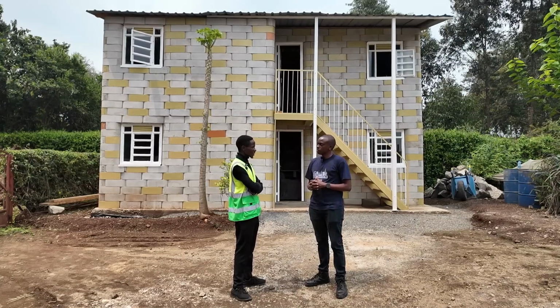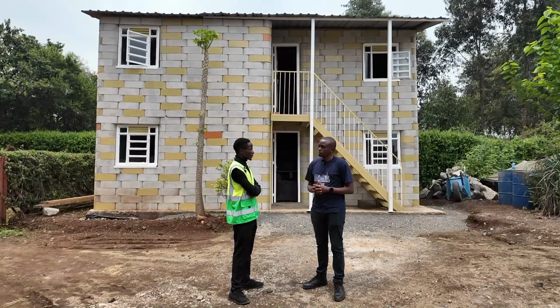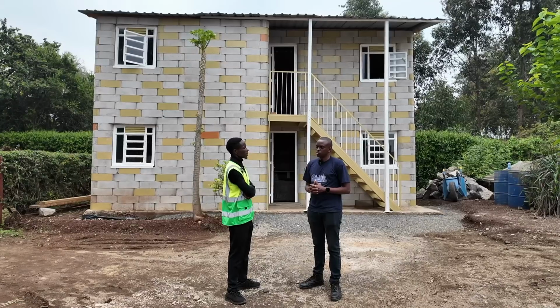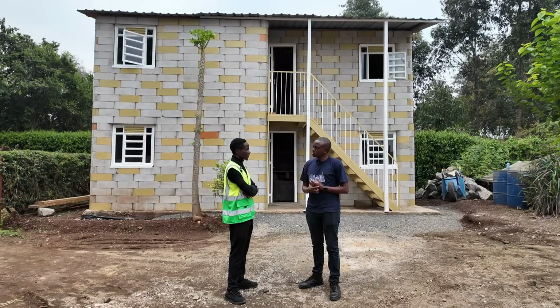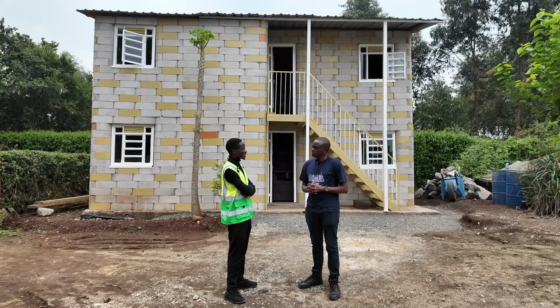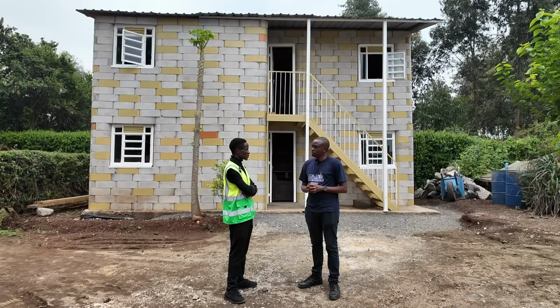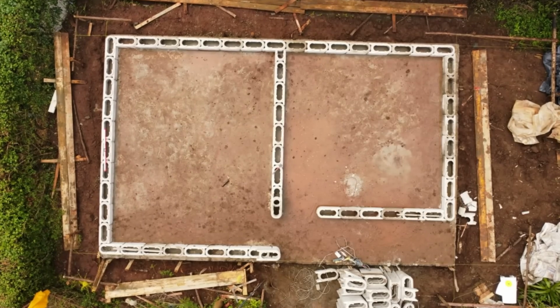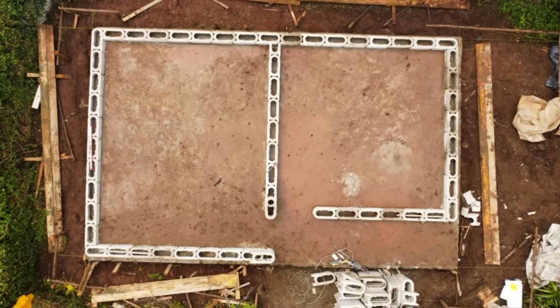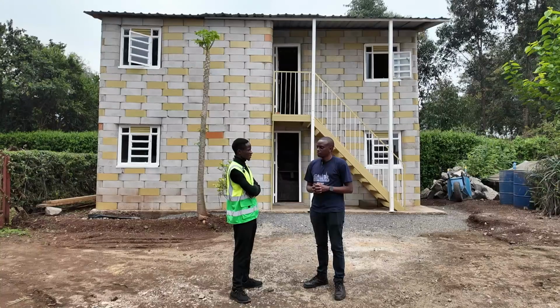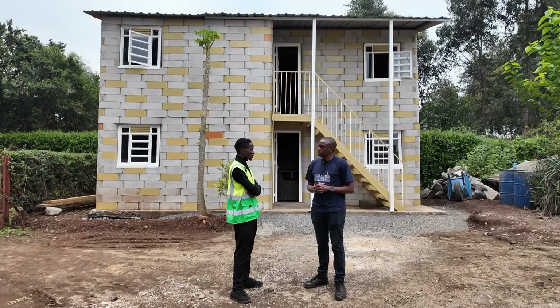Once you've done your setting out and the blocks are perfectly laid, you fill the first course with mortar up to the height of half of the twist block, and then you wait for it to cure a little bit so that they are firm, so that when you're doing progressive laying of the blocks, you don't move them. That is how we integrate it to the foundation.